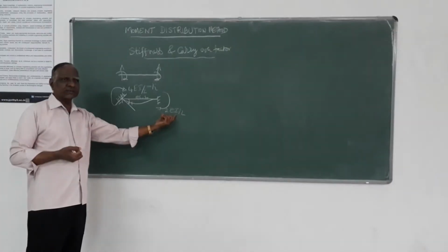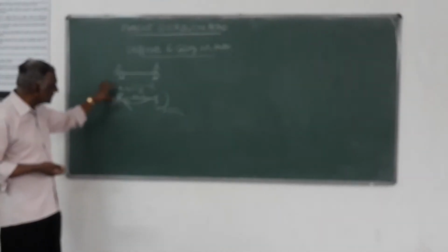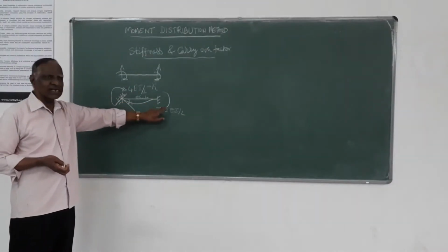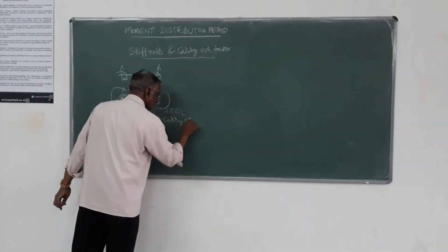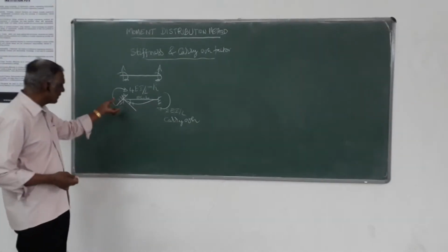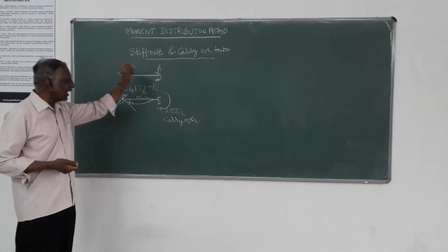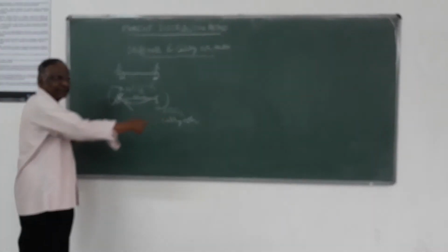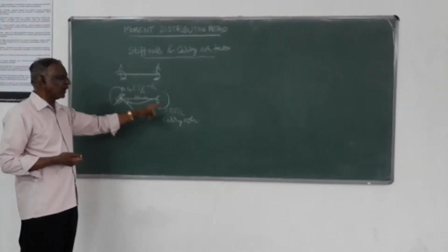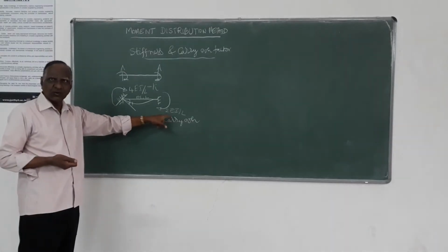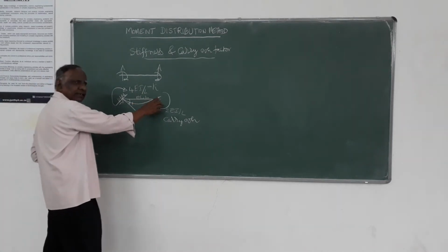This force developed in causing the unit displacement, we call the carryover factor, because the force is carried, equal to half its value, to the other end. Same thing will happen here also.